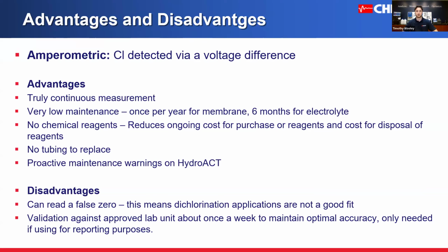and generally once every 6 months, you want to change out that electrolyte. That is something that pretty much anyone that works at a plant can do. We are able to teach that really quickly. We'll go over the electrolyte changing. But those of you that own these type of probes have probably done it yourself before.